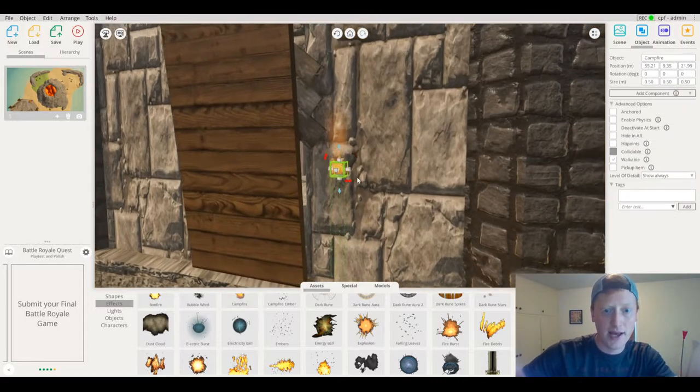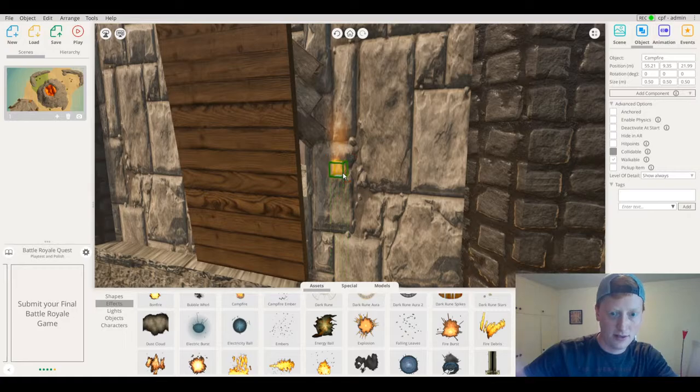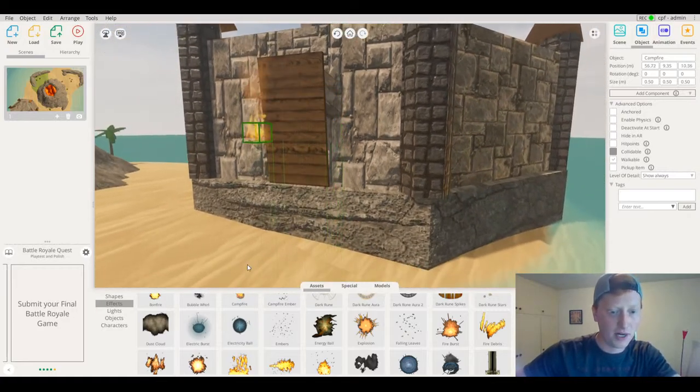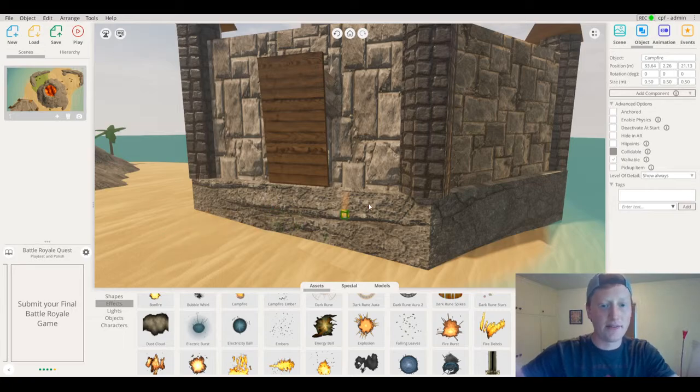Yeah, so we'll start with that, and it's going to be a little bit hard to make that on my wall, so I'm going to make that on the ground here. That tool that I'm using right now basically allows me to stack this. We call it auto stack. You can just put that fire or any object really while holding the shift key, and it just zooms to any surface that your mouse pointer is on, and it moves around like that.